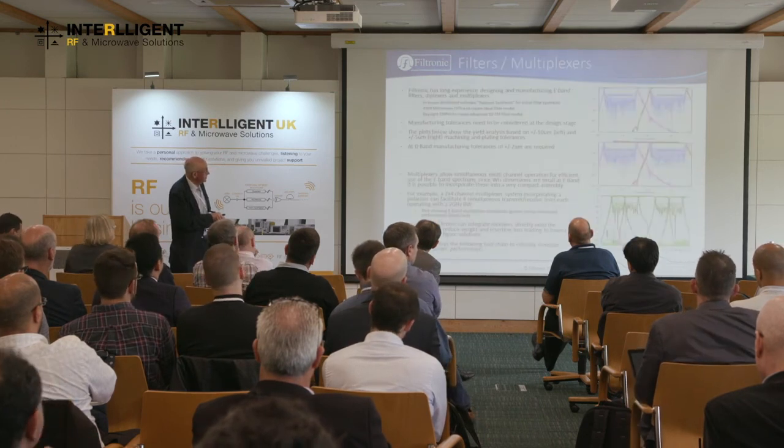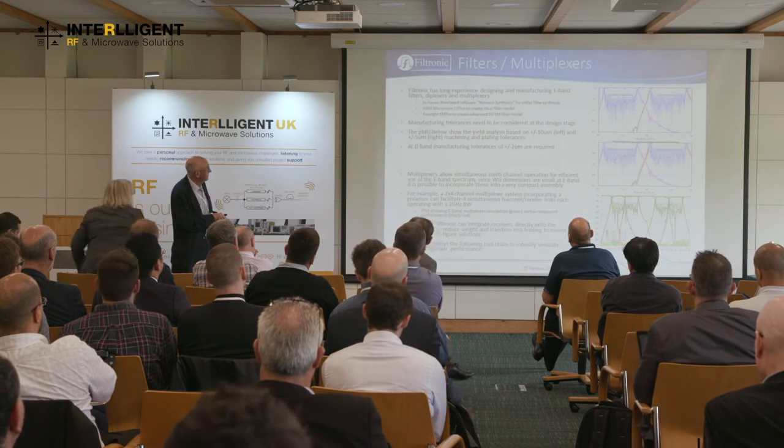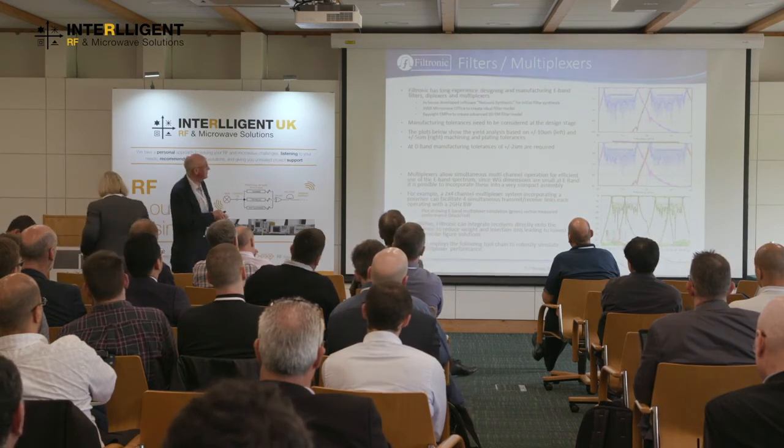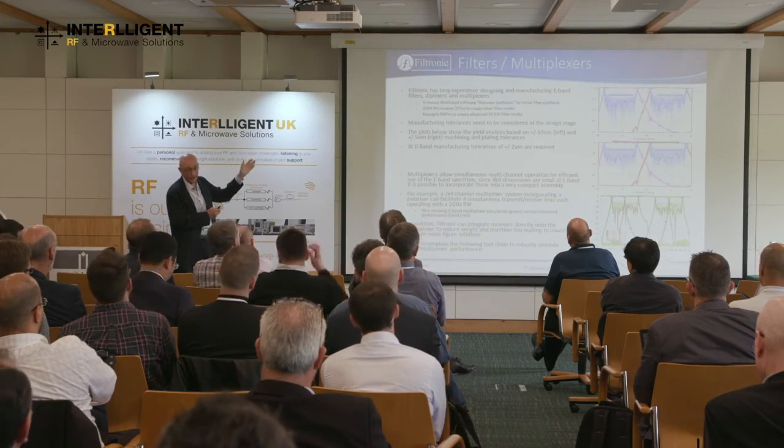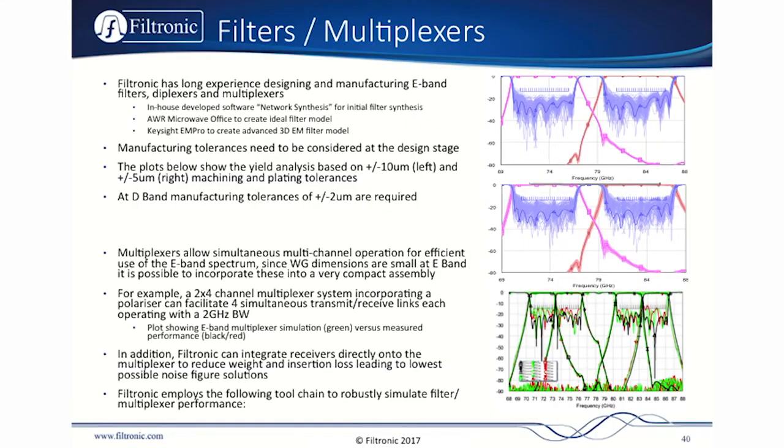Right, I think I'm probably getting to the end of my time. But the last thing is filters. So diplexers, we design diplexers, and we tend to integrate those into the module. We can also do multiplexers though. I mentioned multi-channel systems where you might want to have two 2 gigahertz channels separated by 3 gigahertz. So we also have multiplexers, so you can have an integrated transceiver with multiple channels.